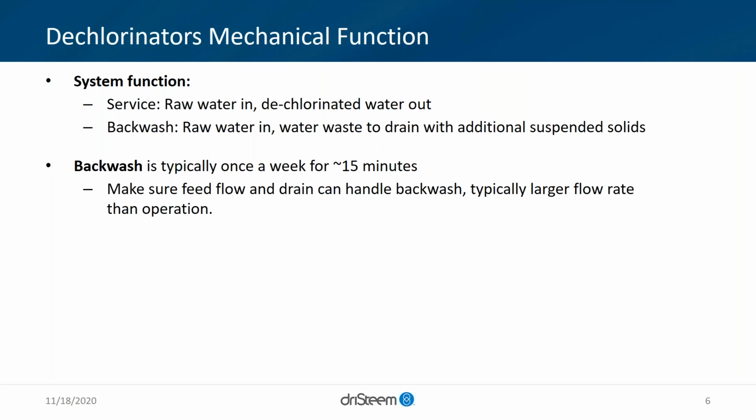Backwash, again, simpler than a softener. It's one cycle that it goes through. It's typically about 8 to 15 minutes, depending on your site conditions. What that backwash is mainly doing is reversing that flow, lifting that bed up, and removing any fines or suspended solids on the top of that bed. That's very important for the sake of the mechanical system. The more solid you have on top of the bed, the more restriction in your system. And really, if you choose not to do it, that restriction can build over time and you can have dynamic pressure issues.